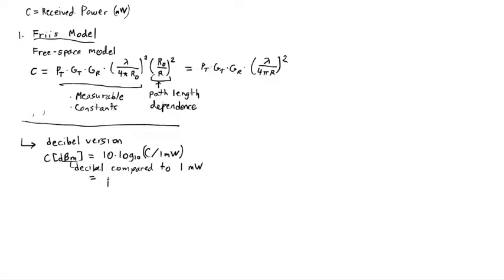So I'm going to get the transmit power in dBm plus the antenna gains in dB. Now, antenna gains don't have units of milliwatts because they are always something that multiplies the true power. The gain is a unitless quantity. So when I take the dB of a unitless quantity, I don't need to refer to 1 milliwatt. I'm referring to 1, and when we refer to 1, we're just talking about regular plain old dB.